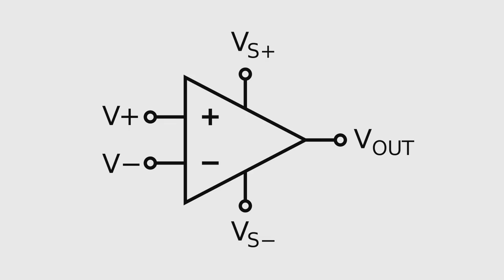The popularity of op-amps as a building block in analog circuits is due to their versatility. By using negative feedback, the characteristics of an op-amp circuit, its gain, input and output impedance, and bandwidth, are determined by external components and have little to do with temperature coefficients or engineering tolerances in the op-amp itself. Op-amps are widely used in electronic devices today, including a vast array of consumer, industrial, and scientific devices.